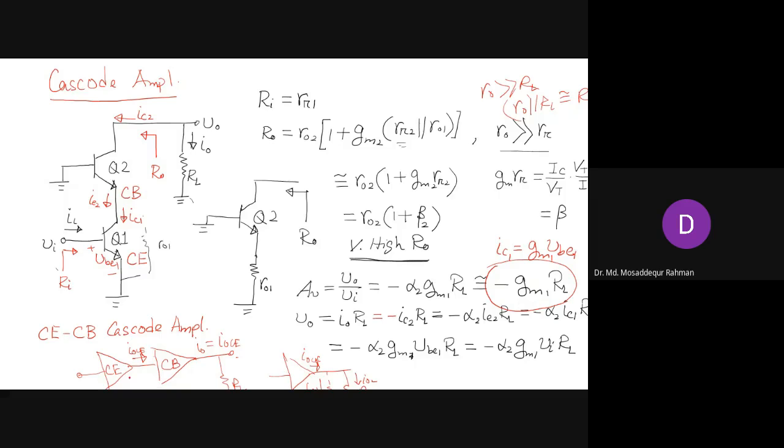Now, when you are adding this current buffer, the buffer is transferring the whole of the current to this, right? Because the current here, you still have this, but it will be very negligible, because here you have very low input resistance. So most of the current will flow here instead of going into here, right? So that is how the circuit will work, and that is how it will make a difference. The gain in this case will be independent of the output resistance of the component. Is that clear, guys?